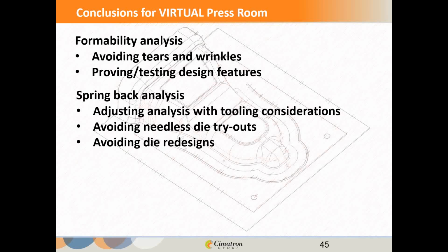So we threw a lot at you here in just a few minutes. Those are a lot of simulations. We tried to condense about 6 hours of work so that you can see how all these tools work together. Again, the idea is we want to look at the formability of the part and really analyze it and understand it so we're not tearing and wrinkling.